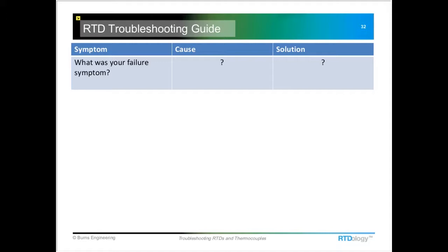And then the probe should be fully immersed. If you've got a really long probe, probably 4 or 5 inches of immersion would be sufficient. So, okay, I hope that's the right answer if I interpreted that correctly. If not, let me know.